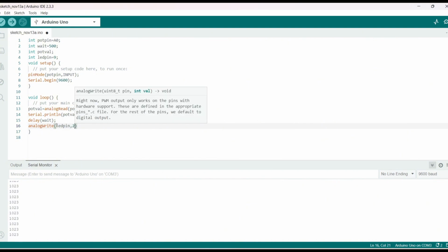And normally we'll have to set it up as a certain number on that 8-bit range. That's from 0 to 255, 0 being the lowest, that's off, and 255 being the highest, that's on. That's maximum brightness. I could put it at any value in between, like 200 or 125, any number in between. But now as we toggle the potentiometer, this number changes.